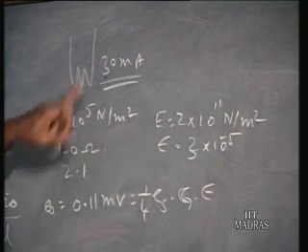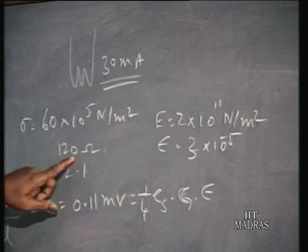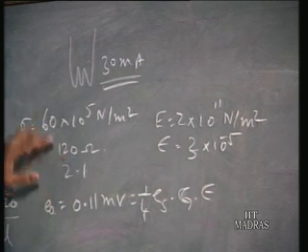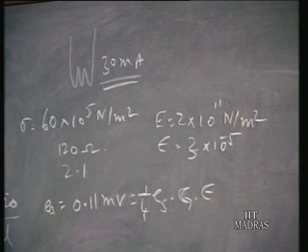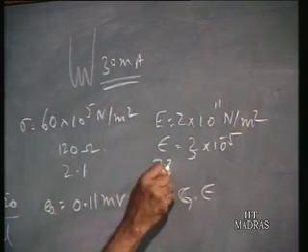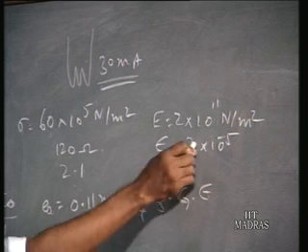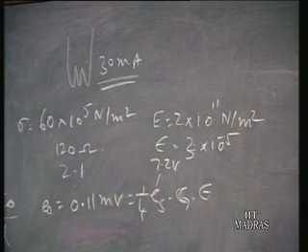For 30 milliamp and 120 ohm resistance, you have got 240 ohm across this voltage supply. So 240 ohm into 30 milliamp running will give rise to a voltage of 7.2 volts. So 7.2 volts supply ES, and G is 2.1, epsilon we have found out. So we find a voltage output of 0.11 millivolt.